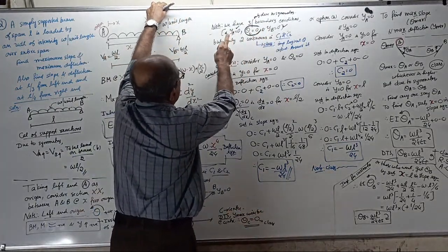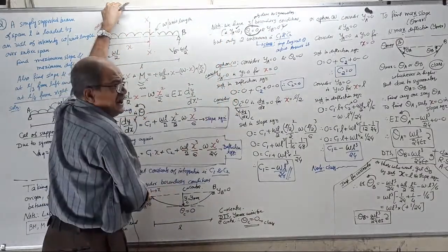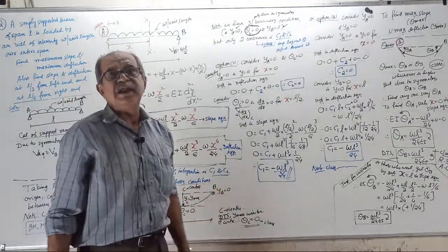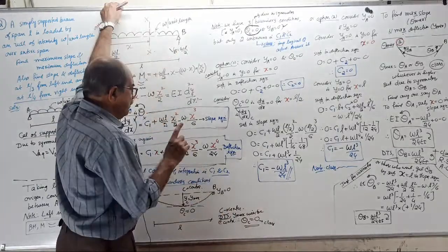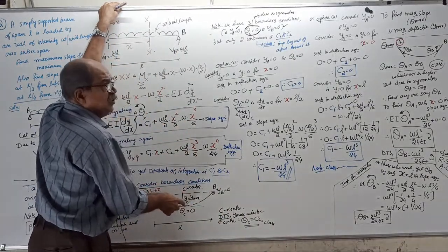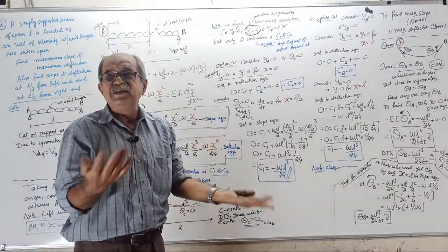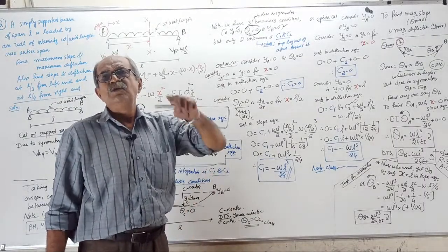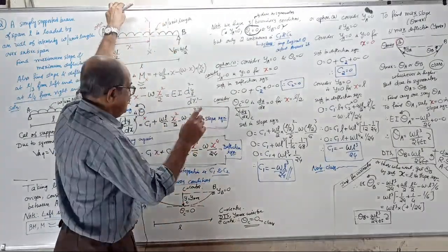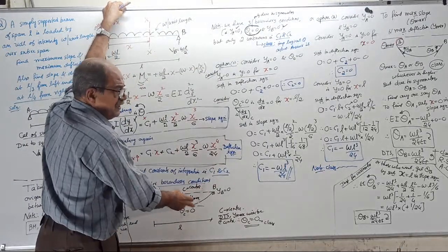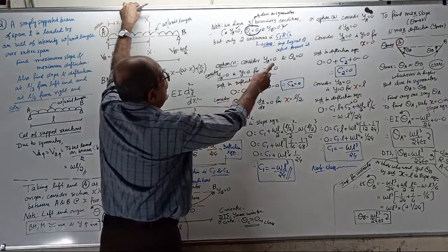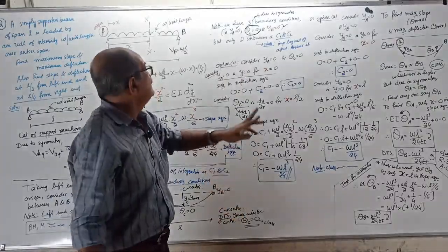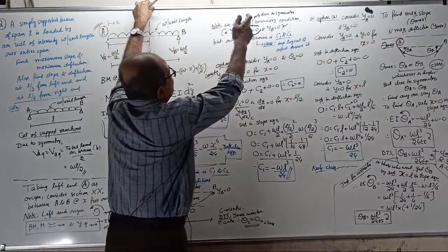You can use either, start from here, deflection at A 0, go to center, slope at C 0, over. Don't use deflection at B 0. Because if you use Ya 0, theta 0, it is as good as using Yb 0. Yb 0 is not an extra equation, it will be automatically satisfied. Or, do one thing, don't use the slope. Use Ya 0, Yb 0. That's what you are doing in all Macaulay's method. Then it is as good as using theta c 0.